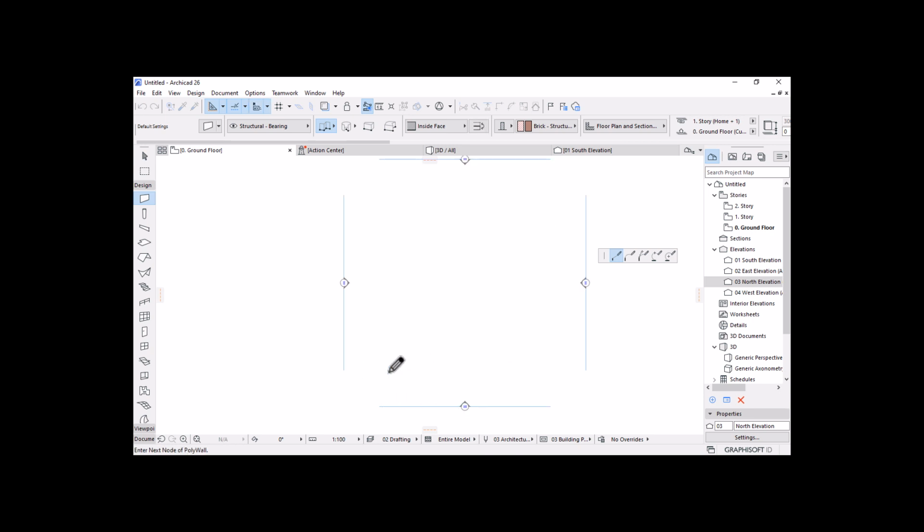Because it's a continuous placement of multiple walls, I'll go up again to the next wall, which is going to be around 6.2, which is 6,200 millimeters, and then hit enter. Then I'll go on the left side horizontally and key in 3.9, which is 3,900. Hit enter, and then I'll go down back by 1.2. Hit enter. We'll move to the right and reference with this guideline to close over.